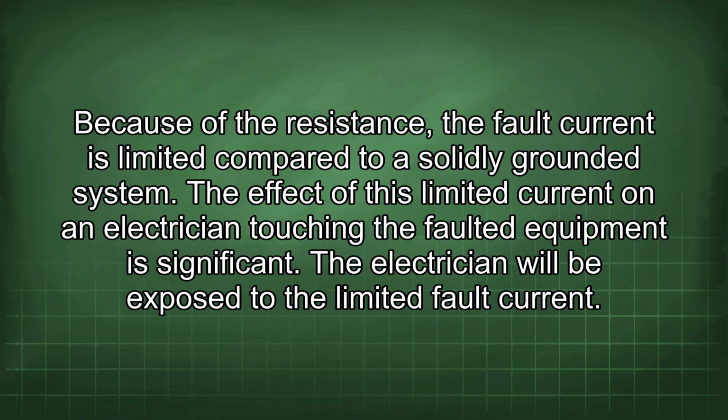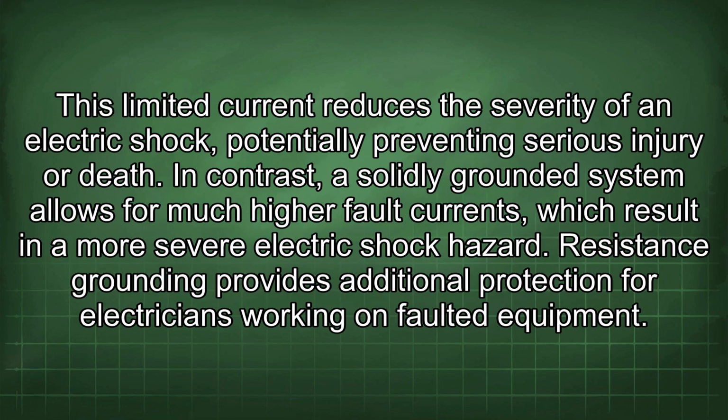The effect of this limited current on an electrician touching the faulted equipment is significant. The electrician will be exposed to the limited fault current. This limited current reduces the severity of an electric shock, potentially preventing serious injury or death. In contrast, a solidly grounded system allows for much higher fault currents, which result in a more severe electric shock hazard. Resistance grounding provides additional protection for electricians working on faulted equipment.